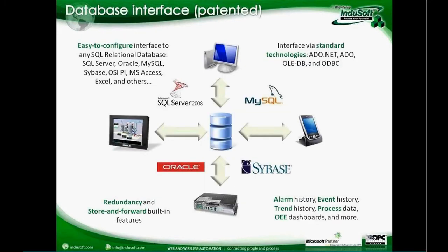Database connectivity. From InduSoft, you can save and retrieve data from any SQL relational database using standard technologies like ODBC, OLEDB, ADO, ADO.NET. Some examples here are SQL Server, Oracle, Sybase, MySQL, and we have many customers that created templates or standard applications that can be deployed on different end users.